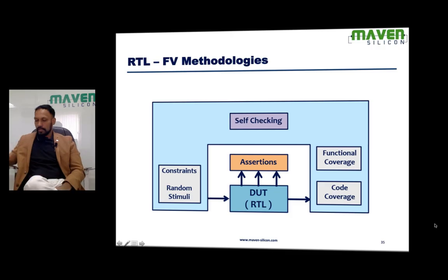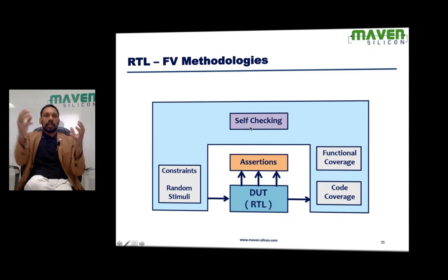Look at this. We have created the SystemVerilog test bench. It does random simulation. But what the test bench does is data integrity checking. What it means is the scoreboard that we have implemented as part of the test bench compares the packets. It collects the DUT output and compares the output packets with the reference packets. It's called data integrity checking.